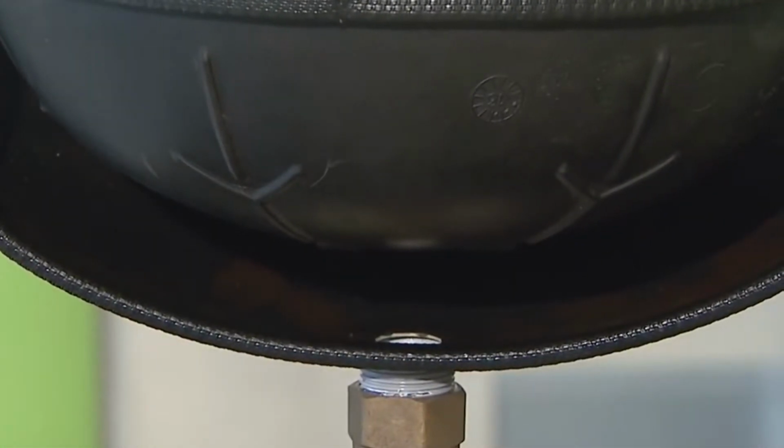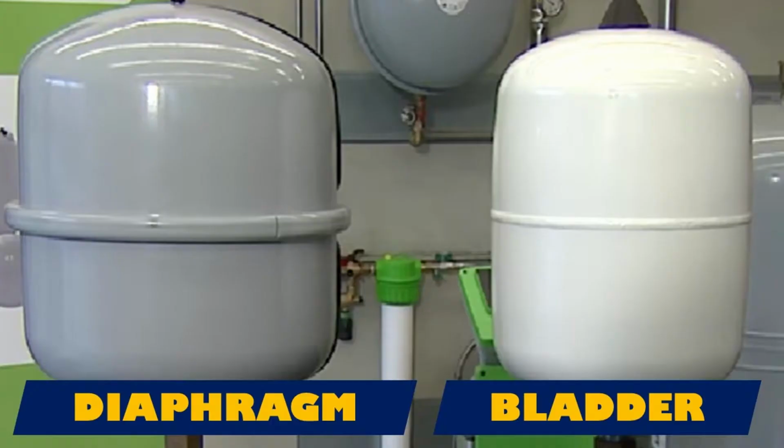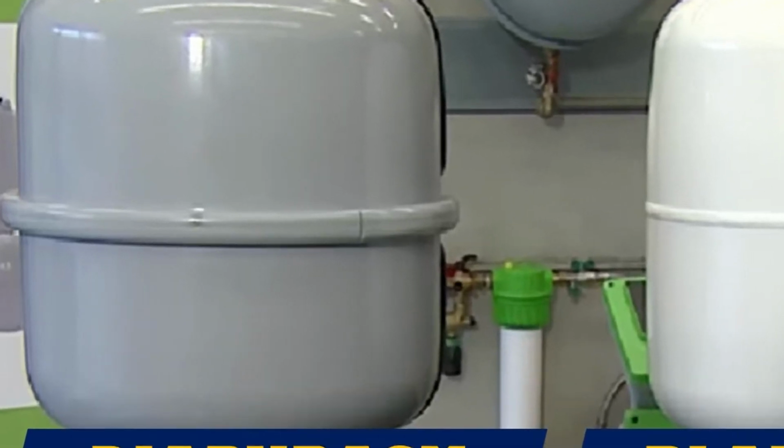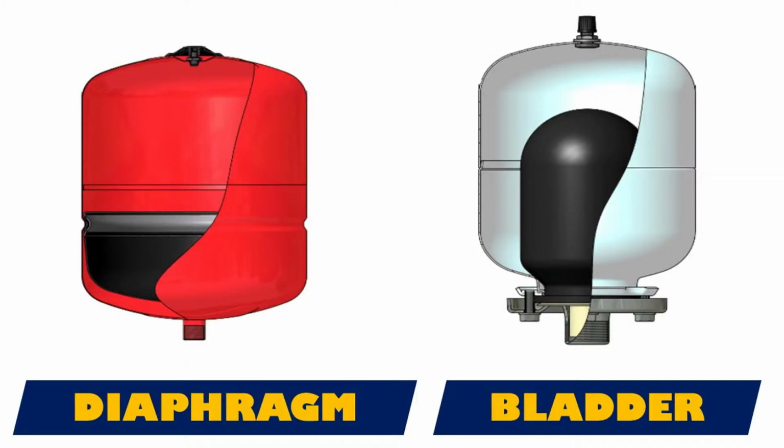In a vessel with a diaphragm, the membrane is fixed in the middle of the body. The bladder membrane is attached to the flange. Externally, they can be distinguished by the type of connection. A tank with a diaphragm has a larger connection, while a tank with a bladder has a flange.